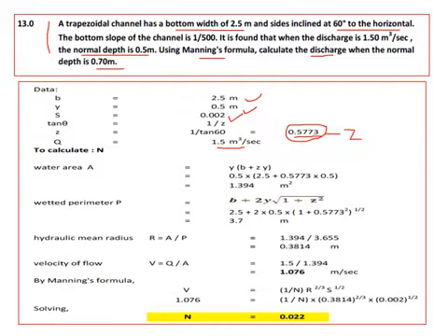So now we know the depth of flow as 0.5. When the depth increases to 0.7, discharge also increases, so the corresponding 1.5 will increase to something else. Therefore for the first set of calculations, 1.5 meter cube per second is given. That will enable us to calculate n. Using this n for various sets of data, when the depth increases, we can find the new discharge.